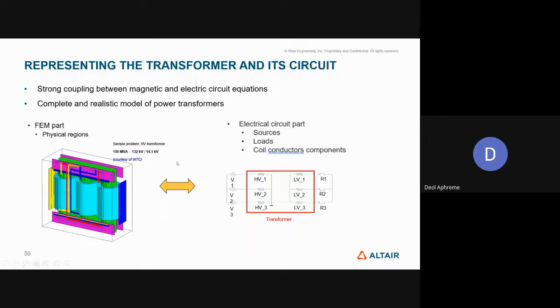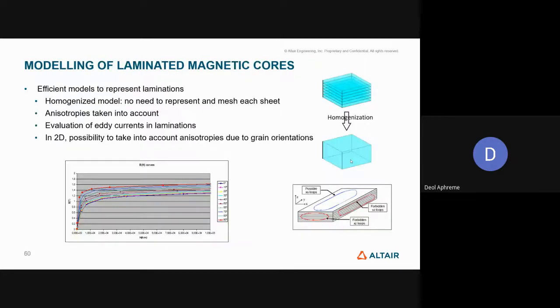So as you can see here, there are R1, R2, R3, which speak about the secondary resistance. This is a component that you will have to compute from the resistivity of the material and give as an input. Flux will not automatically compute this, but if you're in the preliminary stages of your design, you can give some random value, and then just check the reaction, what sort of resistivity you expect to have based on your previous designs. All this can be visualized.